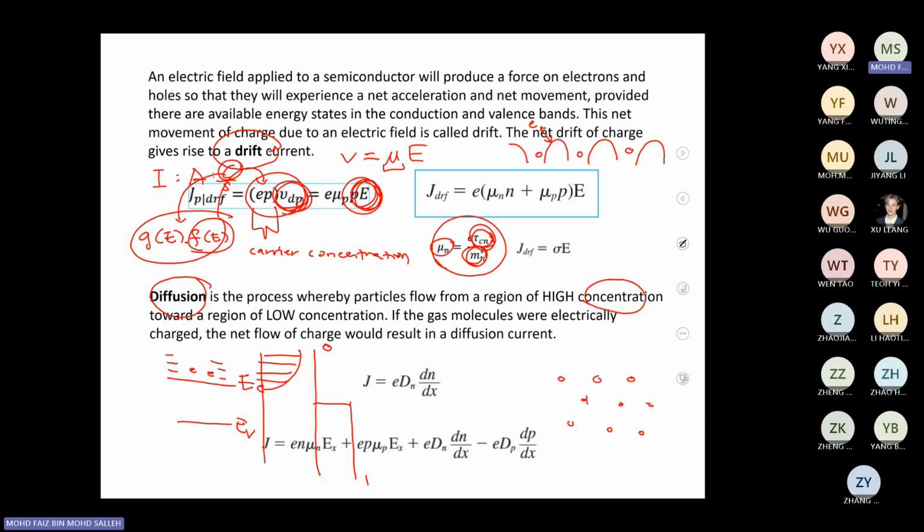Okay, so by using this kind of scattering process, effective mass, mobility and so on, we can estimate how much current there is when you apply the electrical field, when you know these material properties and the number of electrons. Roughly from the equation, you can see that if you want to increase the drift current, you need to increase the carrier concentration, or increase the electrical field, or increase the mobility, by finding a material that has higher mobility. That is for the drift current.